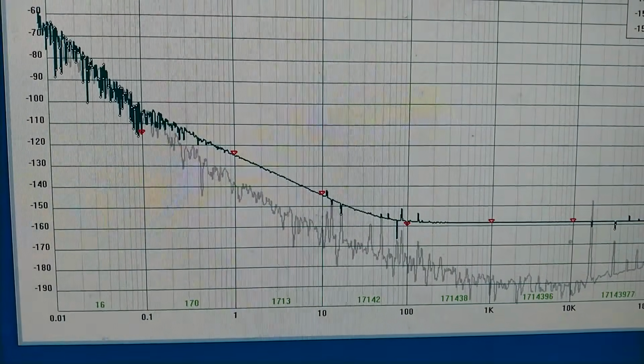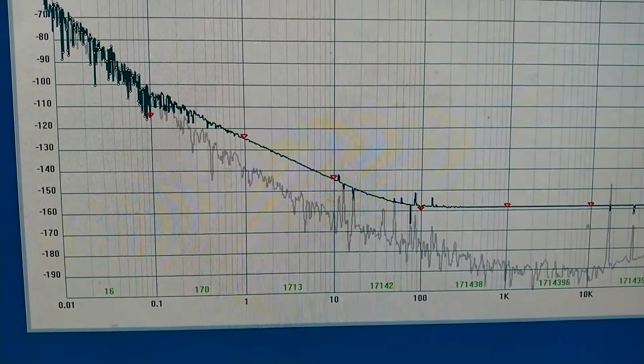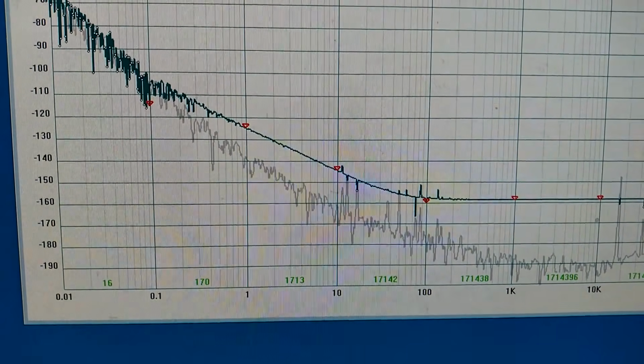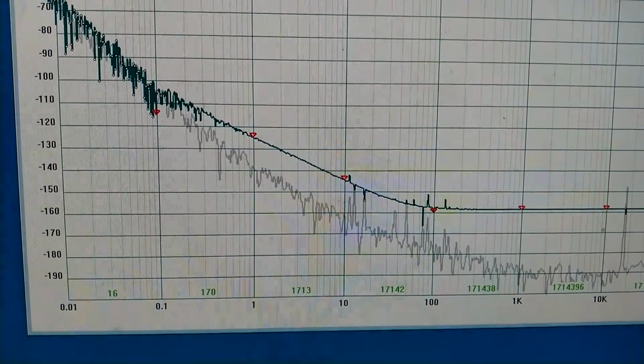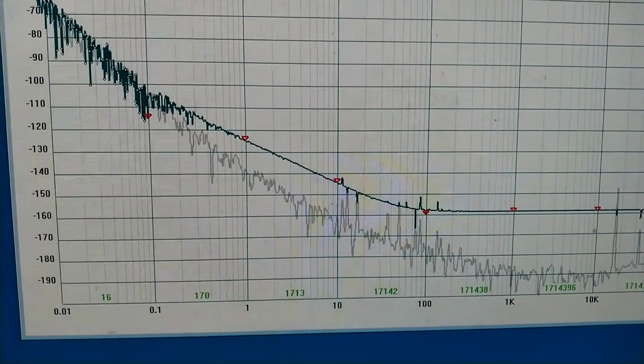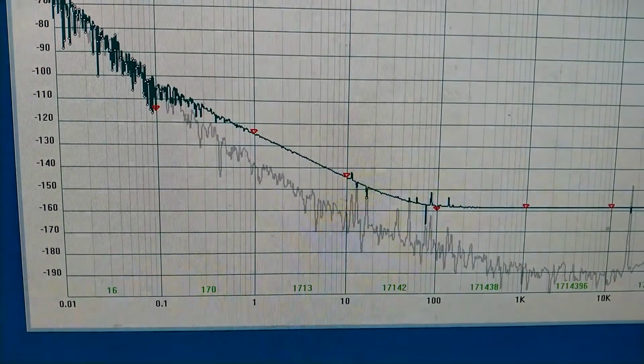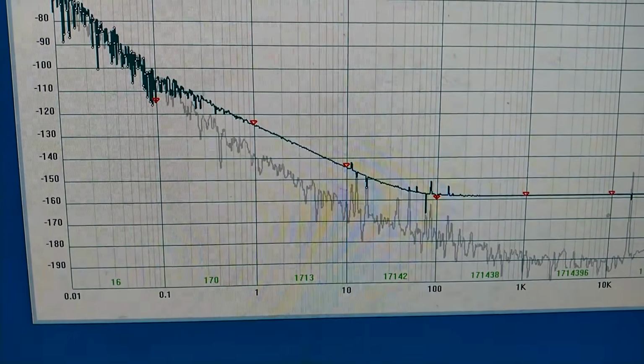The reason for this difference is that the amplifier was saturated before. It was compressed by about 5 decibels when running the full crystal current into the BFR 91A.